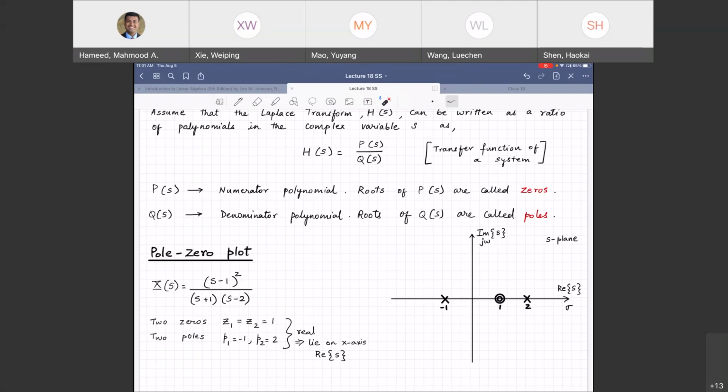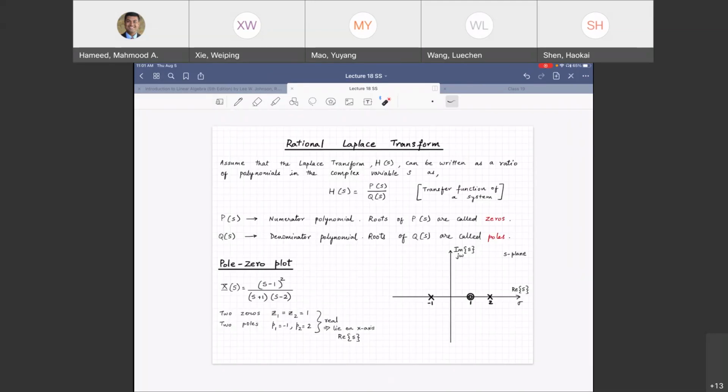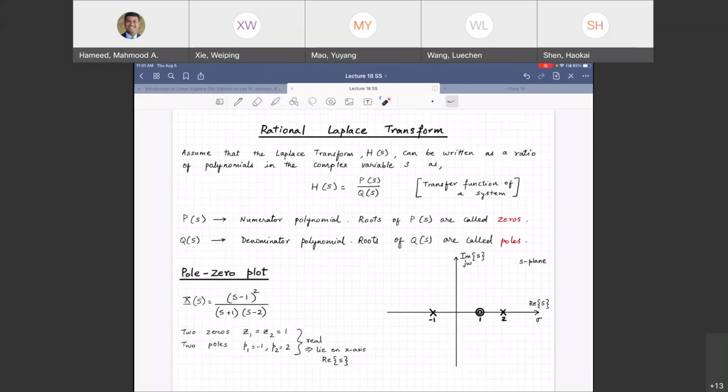That movement, or the poles moving in the S-plane, is called a root locus plot. We will sketch that. We will learn the rules for that. If it moves over and comes to the right half of the plane, that becomes unstable. So in reality, it's becoming unstable, and there's math connecting that. We'll do a demonstration with an inverted pendulum and all that. We'll do something fun related to that. So right now, we are at the initial point of that. So it will seem very simple.